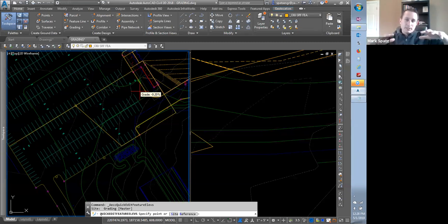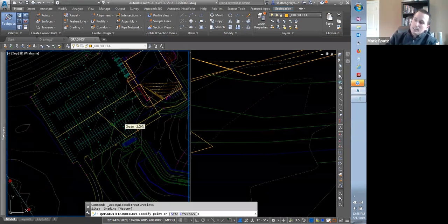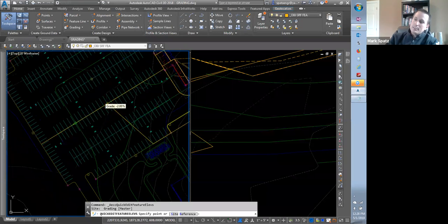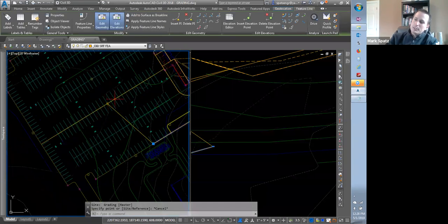So you can get everything drawn, and then you can use a quick elevation to kind of massage everything. Normally in parking lots, you're trying to be 2% cross slopes. That gives nice drainage during a nice heavy rainstorm, but not too steep that car doors are swinging open and hitting other cars and stuff like that. So we've kind of massaged it, looked at everything. One thing we do need to add here, though, is we don't have an elevation point along this, and you do want to, since that's kind of a control point.